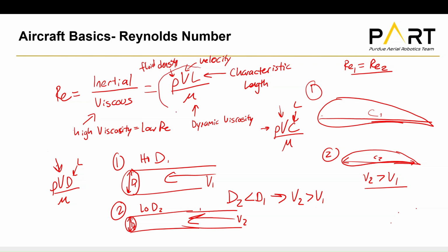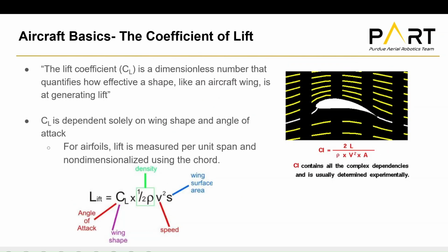First, calculate it using this. Make sure L is the chord length, so the length of your wing. And if you have a variable chord, it's going to be your mean chord length, your mean aerodynamic chord. And ask yourself, does this make sense? And why are we putting in the Reynolds number? So that X-Flyer knows how to have the air actually interact with the wing. Okay? So that's a bit about the Reynolds number. I think I covered that pretty well, to be honest.